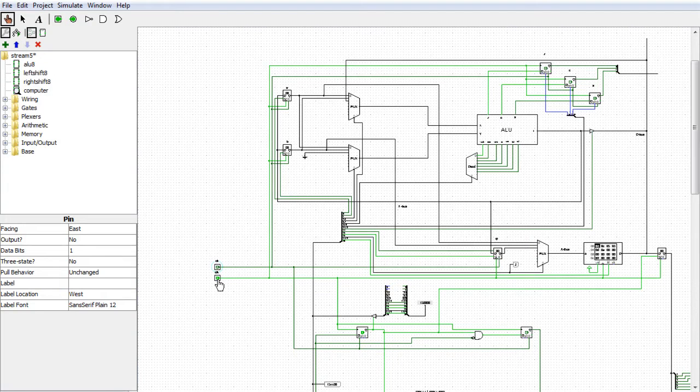So we go low, and that loads the opcode into here, and then high, and then low, high. All right, so we loaded that in there. That's good. High, low, high. Yeah, we load that into there. So far, so good. Low, high. High. We load the new address into here. Low, high, low, high. And we store that into here, and our CPU still has not messed up.